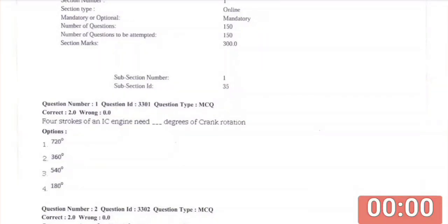Third stroke is combustion stroke, also known as power or ignition. This is the start of the second revolution of the four-stroke cycle. At this point, the crankshaft has completed a full 360-degree revolution while the piston is at TDC or the end of the compression stroke. The compressed air-fuel mixture is ignited by a spark plug in a gasoline engine or by the heat generated by high compression in a diesel engine, forcefully returning the piston to BDC.